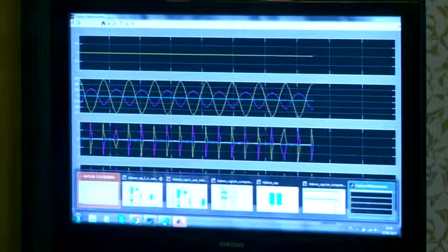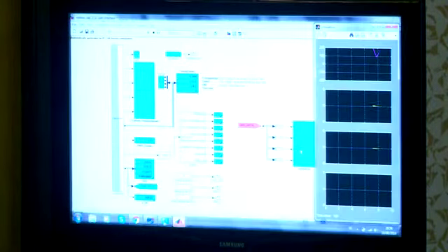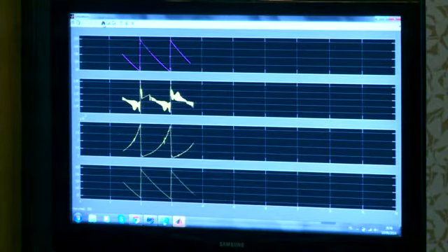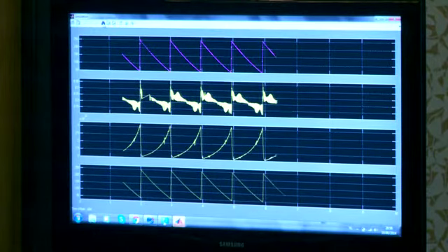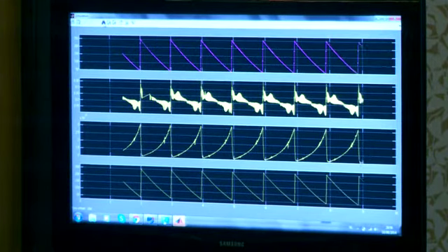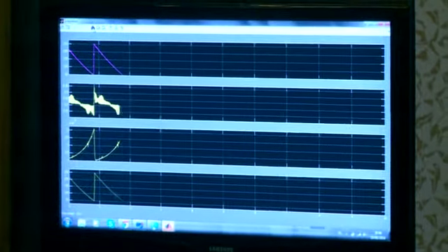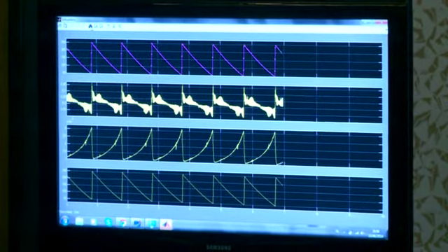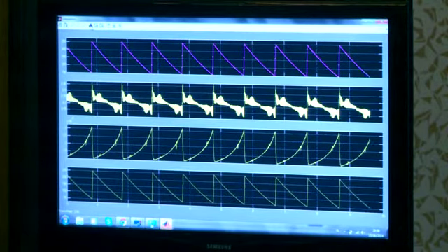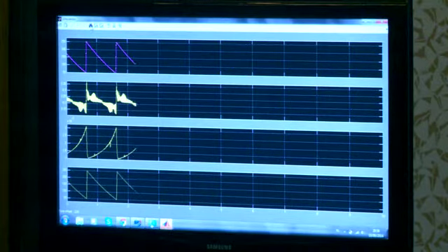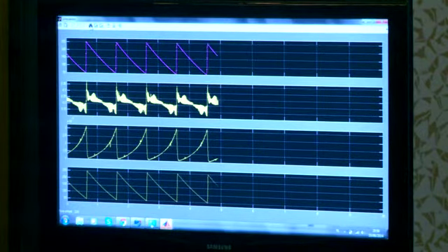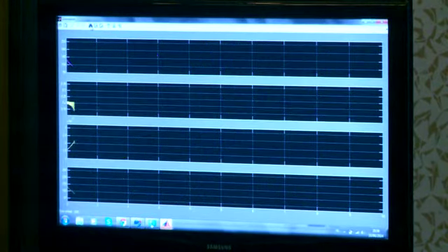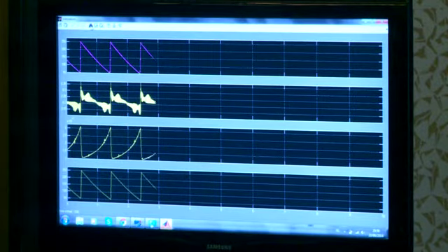On the other side, we have the simulation. This is the set point. The yellow, the upper curve, is the set point which is sent over to the amplifier. The purple one is the actual value. And the second axis is the current being drawn. You see that's a very, very small current, only 0.2 amps, while the measurement accuracy of the amplifier is in the range of 0.05, 0.1 amps.